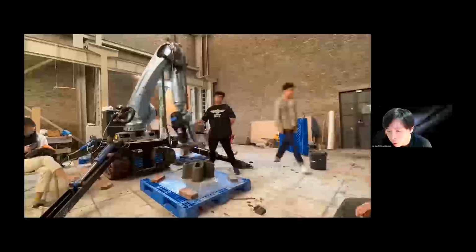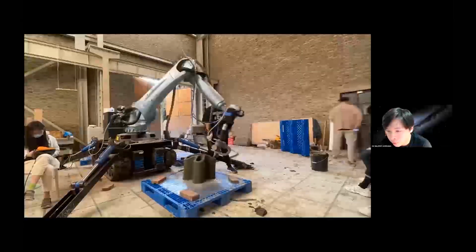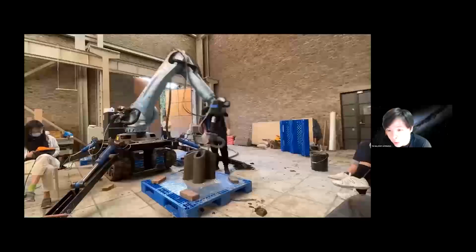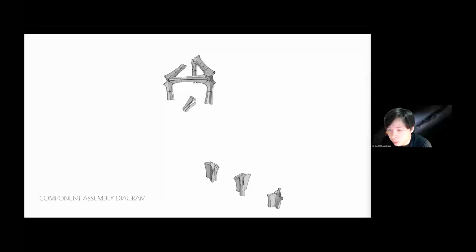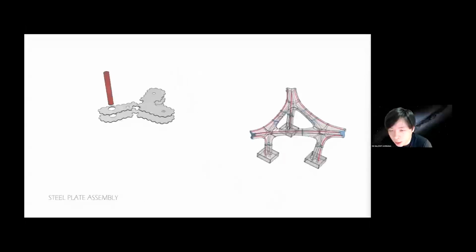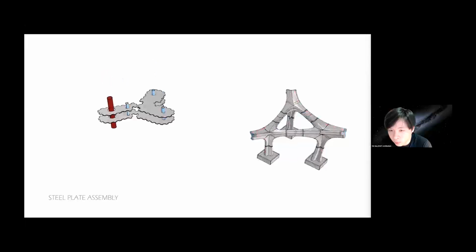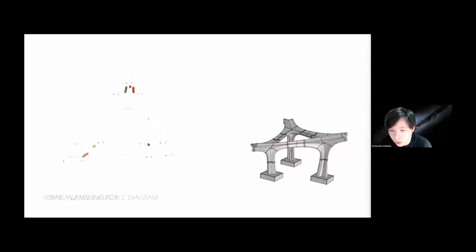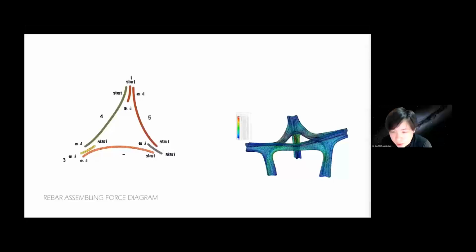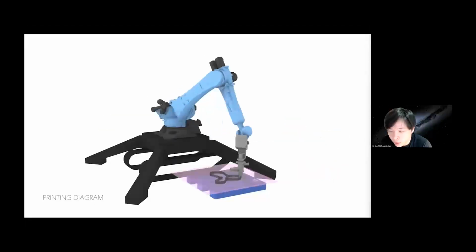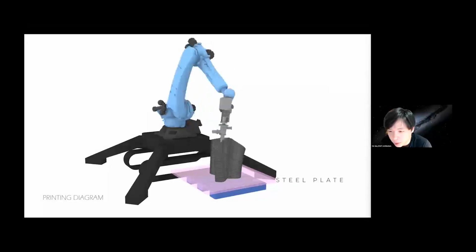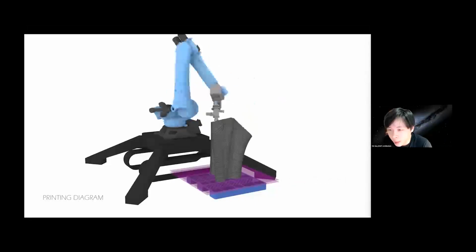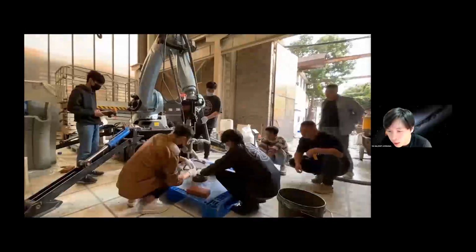Because 3D printing always leaves a hollow empty space in the middle, that's why we use a steel plate for fixing the steel rebar systems. You can see we print a few layers, then add a section of steel plate, which helps with installing the steel bars.